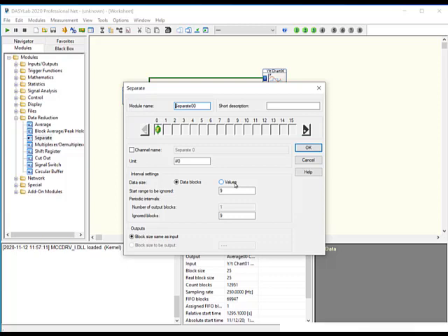If we start with removing data by values, this defaults to keeping a sample for every 10. So you'll skip 9, keep 1, skip 9, keep 1. And in doing that, we are reducing the amount of data by 10. You're starting with a block size of 100, so the output block size should also be reduced by 10.